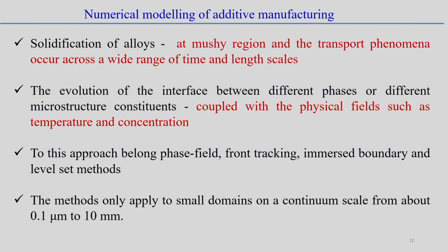In additive manufacturing, definitely it is associated with the solidification process, and solidification of the alloy is very important. What is happening in the mushy zone? Mushy zone means the zone between the solidus and liquidus temperature where the liquid phase and the solid phase coexist. In that case the concentration gradient, temperature, and transport phenomena are very important, that is, how the elements are transported within this very small structure. If you understand this phenomenon, as already mentioned, we need to go for the lower length scale and time scale. Maybe the grain scale modeling approach is required to understand the solidification behavior.